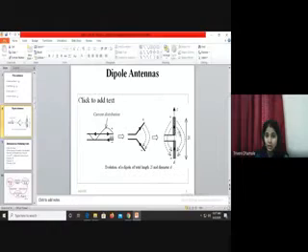So positive and negative, whatever this dotted arrow shows is the electric field, right? How that field is detaching from this antenna in the far field. So this length, whatever the length from this plus to this minus, this is the length of the antenna, and generally it is measured in wavelength lambda.